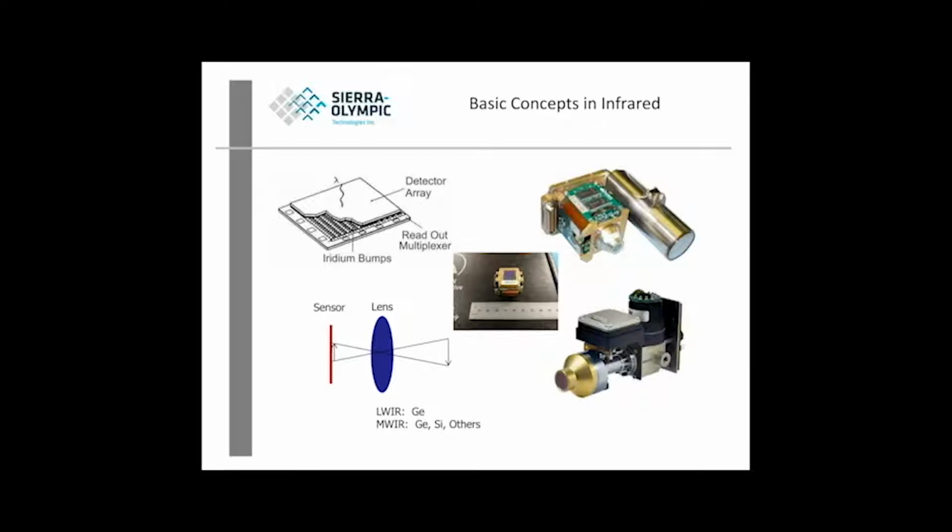It compresses helium, and then the helium decompresses and cools, and you have to remove that heat with that helium. And all of this is with the goal of taking a sensor down to 80 Kelvin or 150 Kelvin, depending upon the type of material. So that's the complexity of a cooled midwave system.